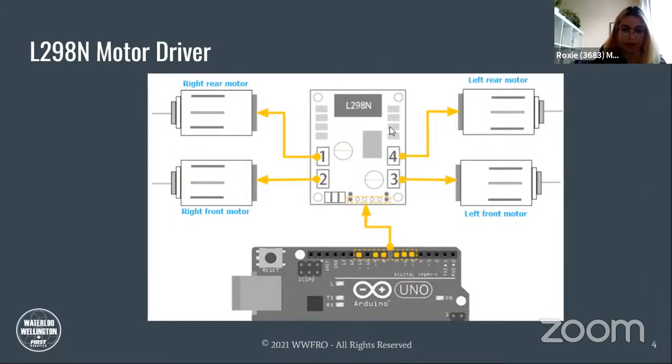The purpose of this module is, it's a motor driver, so it takes power from the Arduino board, which takes power from the battery, and then controls the DC motors. If you look at the top of your robot, your I/O expansion board is split up into rectangles that each have some wires coming out of them.